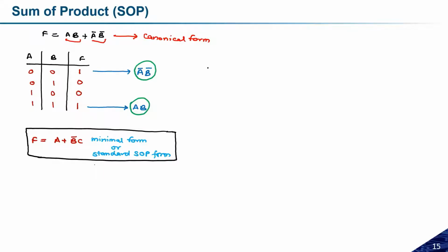Okay, so let us try to make one table. If you talk about a 2-bit number, if I have 2 variables, the total possible combinations are 4. 0, 0, 0, 1, 1, 0, and 1, 1. Okay, whatever we just wrote here. And if we convert this into decimal form, the numbers will be 0, 1, 2, and 3. So we can represent up to 3 if we have only 2 variables. Okay, so let us try to write that and understand what is the meaning of min term. Suppose I have a 2-bit, so I have only 4 possibilities: 0, 1, 2, and 3.